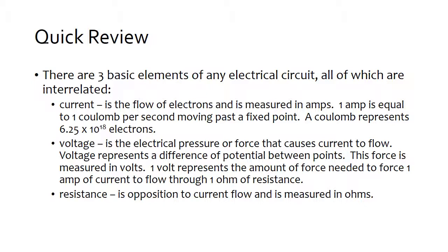Then you'll have another point or terminal that's got an absence of electrons, so it has a positive charge. Whatever the difference in potential is between those 2 points, that's your force that causes electricity to flow, and that's voltage. Remember that this force is measured in volts, and that 1 volt represents the amount of force needed to force 1 amp of current to flow through 1 ohm of resistance.